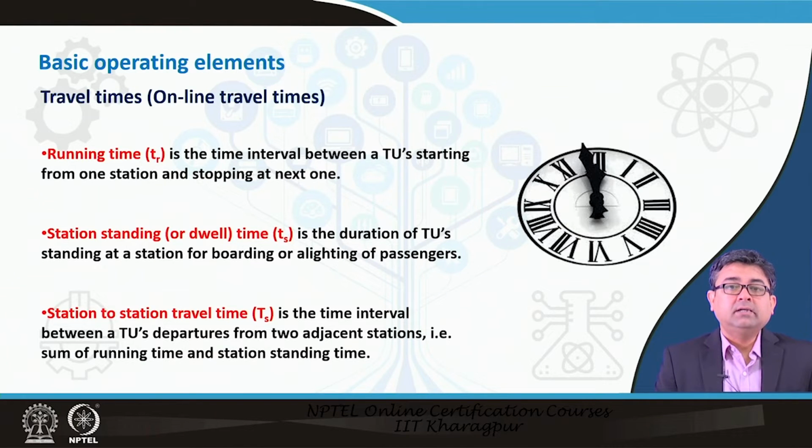Next, when we look at station standing time, which is also popularly called the dwell time, that is the duration of a transit unit standing at a station for boarding or alighting of passengers. As we move forward in the lectures of public transportation systems, you will see that dwell time is a very major factor in determining your overall travel time on a public transportation line.